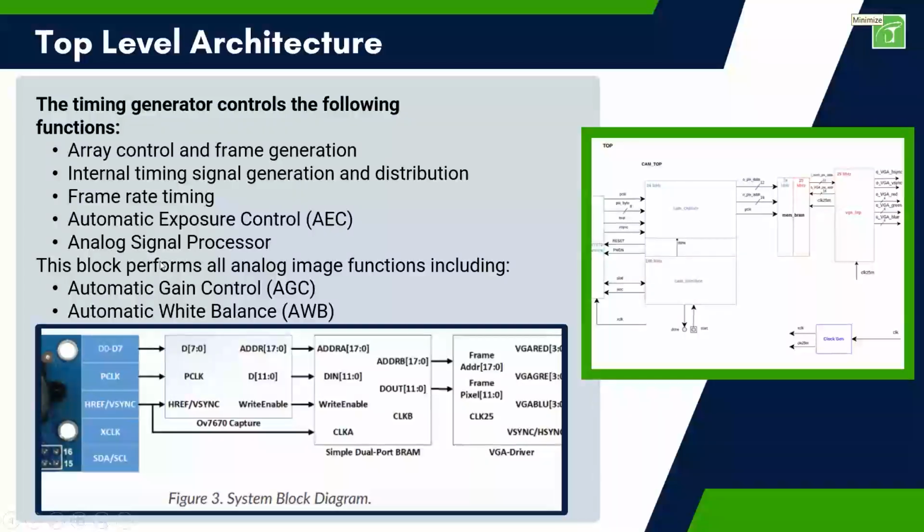So another important factor you have to see in the OV7670 is that the automatic exposure control is completely controlled by our I2C settings. So based on your automatic exposure control and the I2C settings you apply, you are converting this exposure part. You have the independence of changing that exposure.